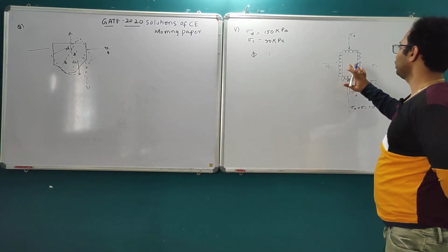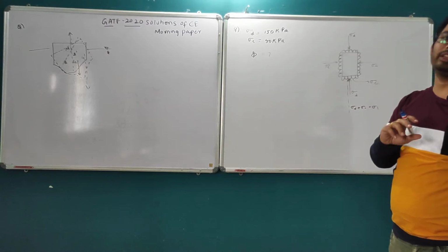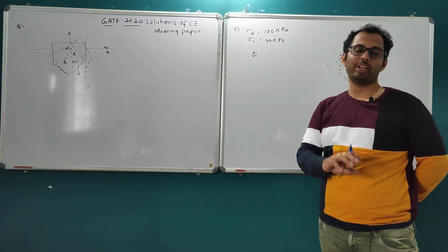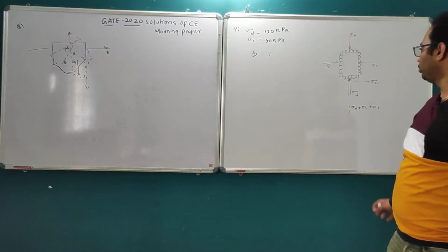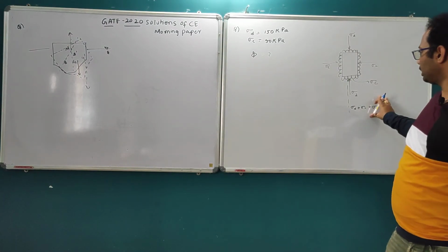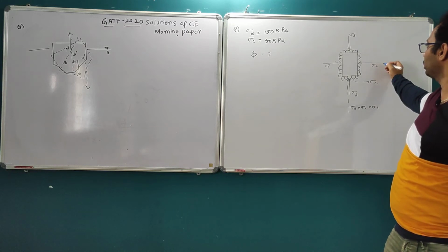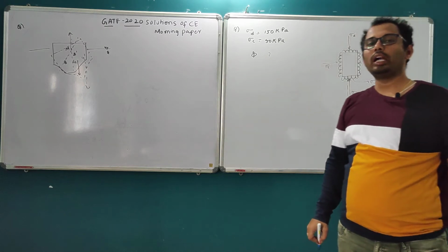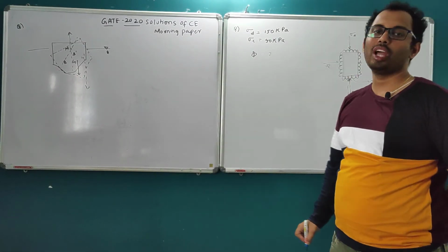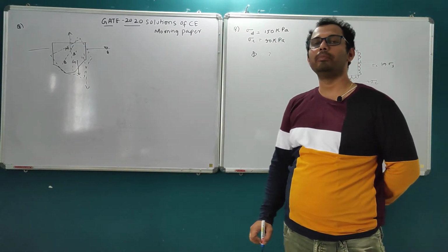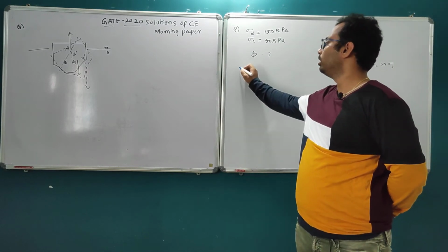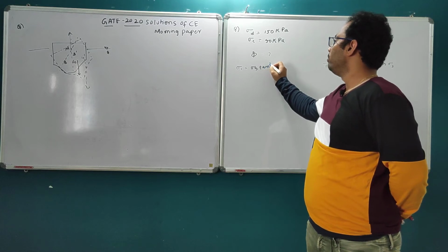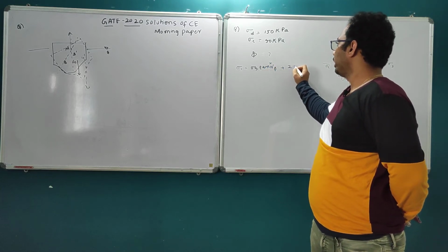So it is simple. In the shear strength topic, we generally use the concepts of stresses and strains and strength of materials. This is major principal stress, sigma 1, and this is minor principal stress, sigma 3. When the soil attains plastic equilibrium, there is a relation: sigma 1 equals sigma 3 tan square alpha f plus 2c tan alpha f.